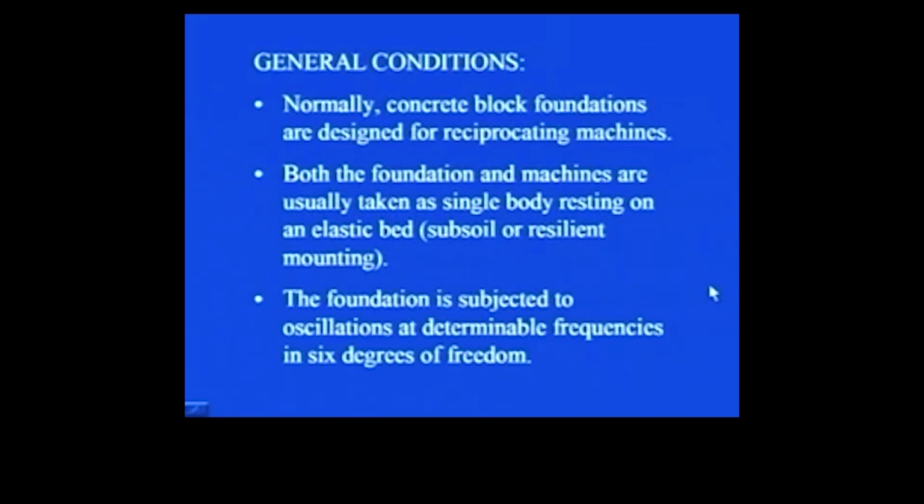General conditions. Normally, concrete block foundations are designed for reciprocating machines. Since we are talking of a block foundation on a reciprocating machine, usually concrete block foundations are designed. Both the foundation and machines are usually taken as a single body resting on an elastic bed, that is, elastic bed means subsoil or resilient mounting.